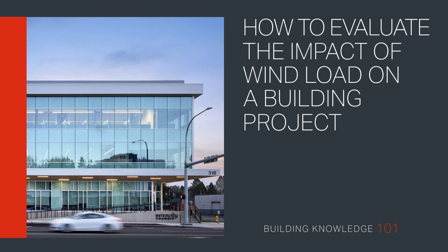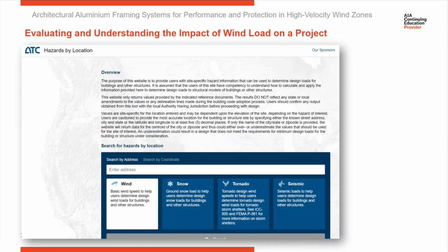In this video, we cover the critical method of evaluating the impact of wind load on a building project and the importance of understanding how this is driven by a project's location. So to start in evaluating what the wind load is for your project, here's a website, ATC. This is a great place to start.